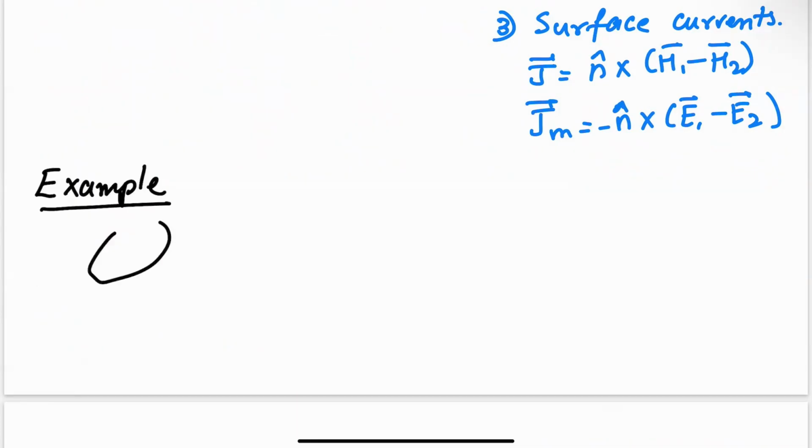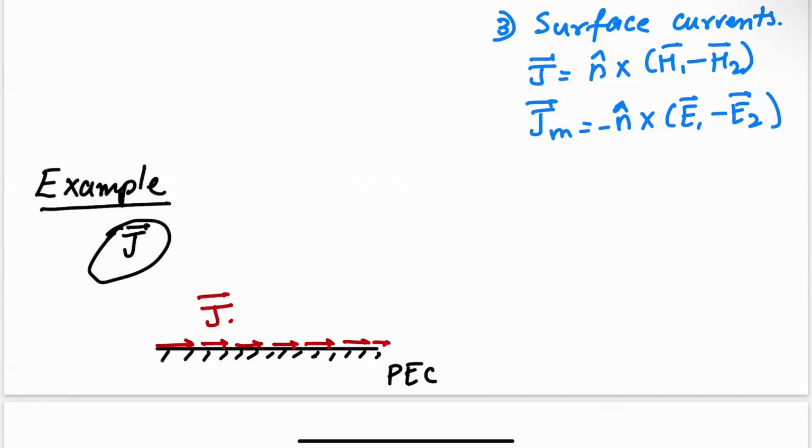So for example, let's take a simple example and see how an induced source can become an impressed source, right? So let's say I have some current distribution. This is my impressed current, which is given to me. And I have a PEC ground plane, some kind of metal plane. And we want to solve this problem essentially, okay? So you'll see that once you solve the problem, there will be some current distribution on this surface, J_S, which is given by n hat cross H, right, to satisfy that boundary condition.